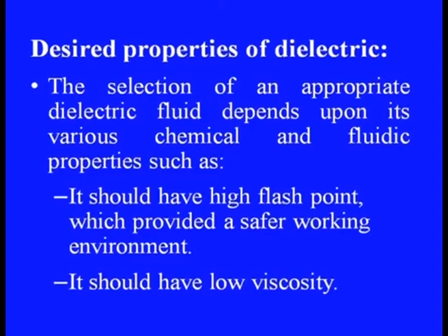Then it should have low viscosity, so that it can flow very easily, as well as flush away the debris produced in that working zone. It should also have higher dielectric strength to minimize the DC arcing, direct current arcing, that takes place during that process.